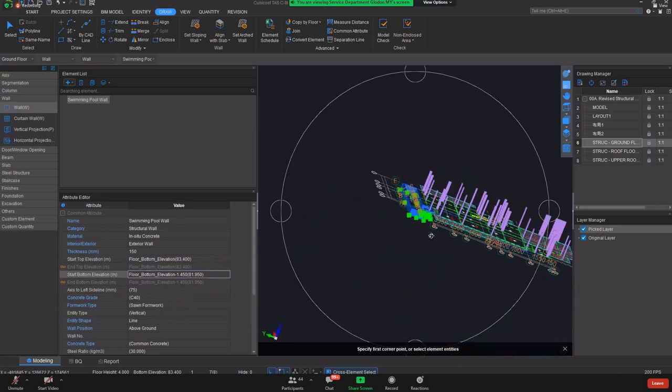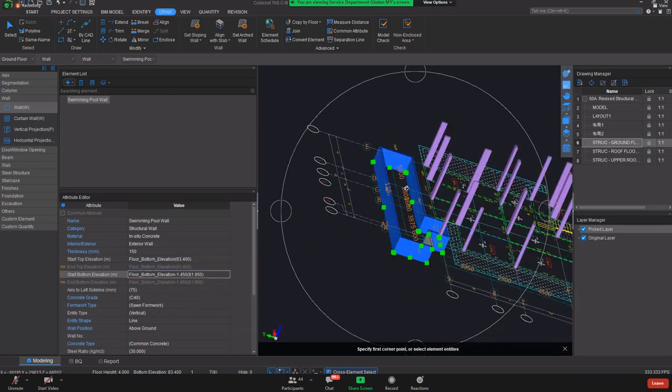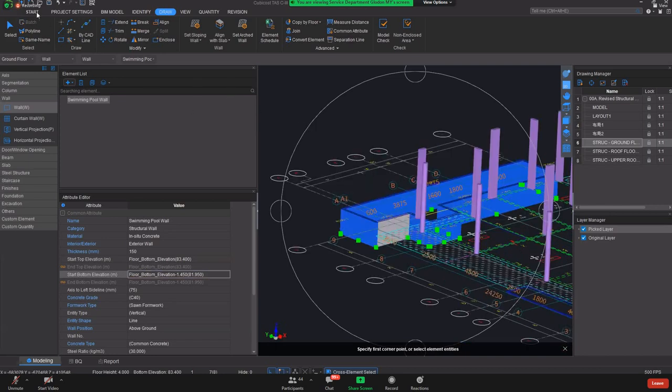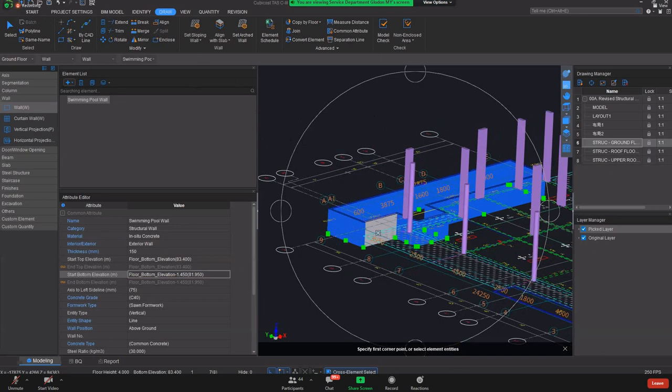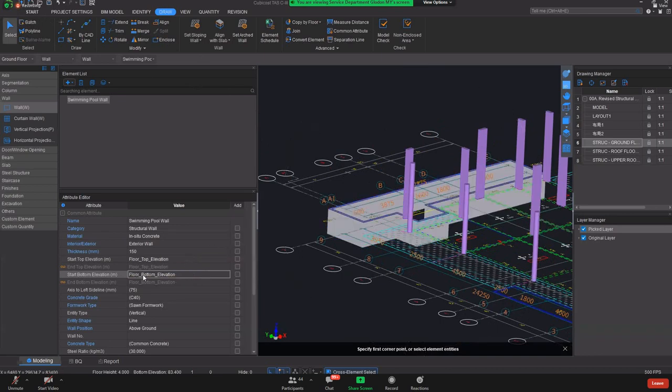In this, I actually introduced two things. The first is you can use batch to batch select the entities with the same entity name. And then if the information is not uniform, is uneven, there will be a question mark shown in the attribute editor.